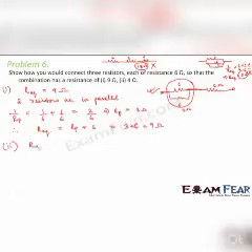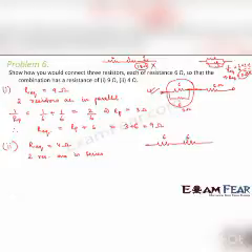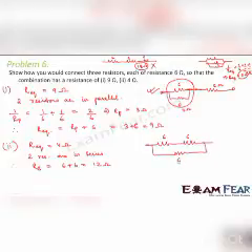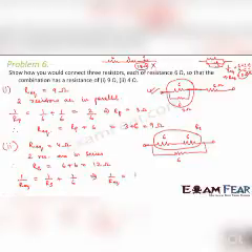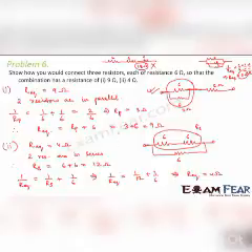Now let us look at the second part where we want R equivalent to be equal to 4 ohms. In this case, let us say that 2 resistors are connected in series. That means this is how we first connect 2 resistors of 6 ohms each. So what would be the series equivalent resistance of these two? 6 plus 6 equal to 12 ohms. Now with these 2 resistors in series, let us connect the third one in parallel like this. So 1 by R equivalent will be equal to 1 by Rs plus 1 by 6, because the equivalent resistance of these two is Rs. So this implies 1 by R equivalent is equal to 1 by 12 plus 1 by 6. So this implies R equivalent is equal to 4 ohms, that is the desired resistance. So therefore this would be the desired combination of the resistors.